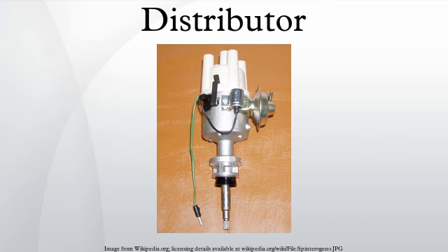The rotor is attached to the top of the distributor shaft which is driven by the engine's camshaft and thus synchronized to it. Synchronization to the camshaft is required as the rotor must turn at exactly half the speed of the main crankshaft in the 4-stroke cycle. Often, the rotor and distributor are attached directly to the end of one of the camshafts, at the opposite end to the timing drive belt.